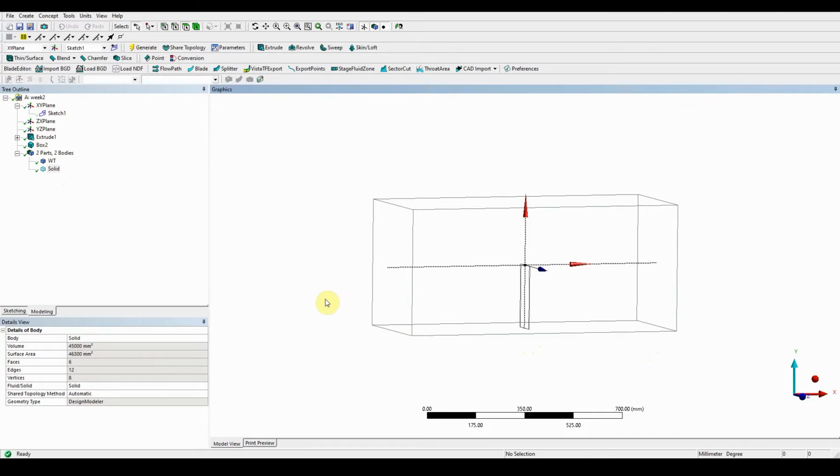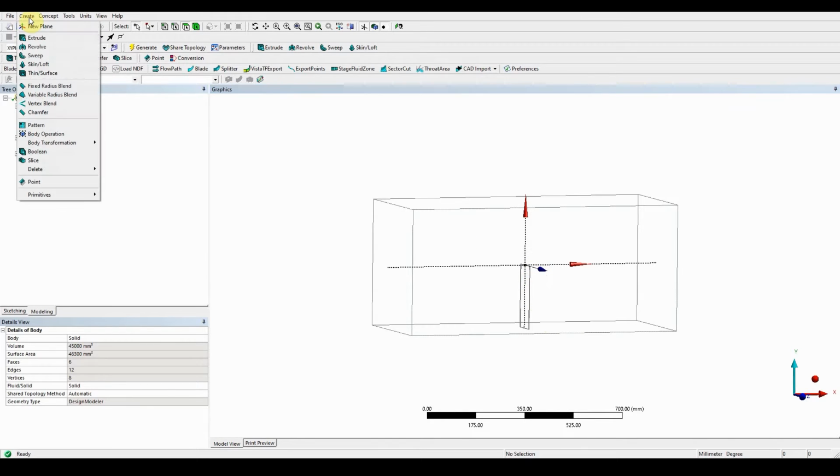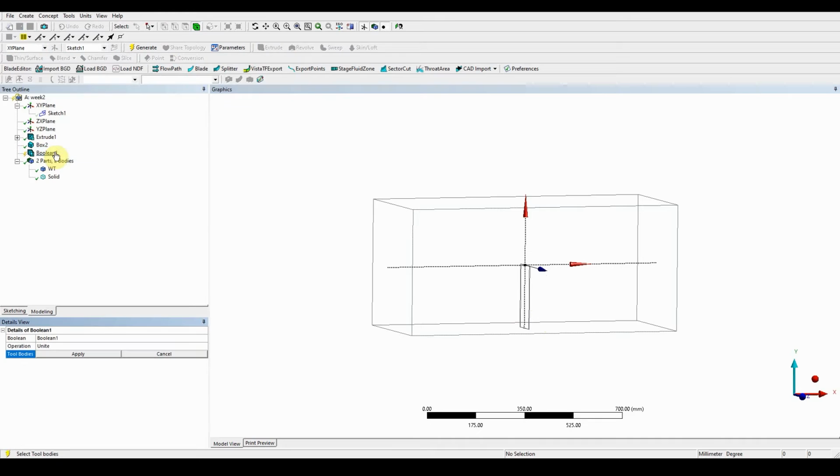So therefore the air coming in obviously cannot travel through an empty void, so it has to go around the shape that is being subtracted, because this whole volume will be filled with mesh, and that mesh is where the calculation will take place. But at the same time, because we're going to be running an FEA analysis, we don't want this plate to disappear, so we'll be using a Boolean function to subtract, but also retaining that actual shape or body. So create Boolean.